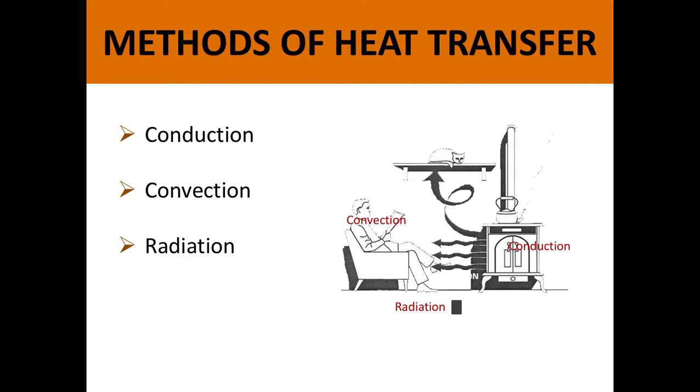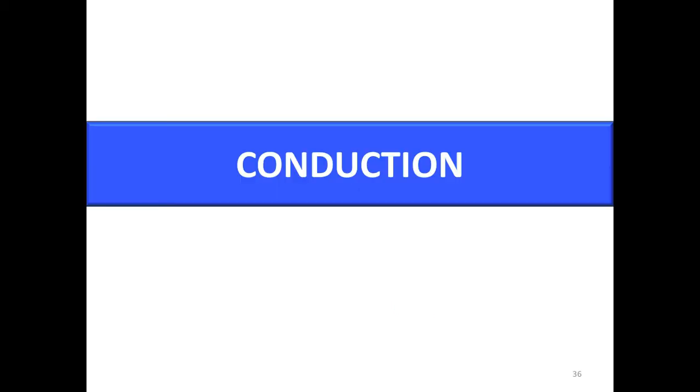Now, why this is important is because when you have heat leaving or entering a home or any other building, it comes in three ways. And you have to understand these three ways so A, you can compensate for it with your sizing of equipment, and B, so maybe you can prevent some of this heat transfer from going on. So our three methods of heat transfer are conduction, convection, and radiation.